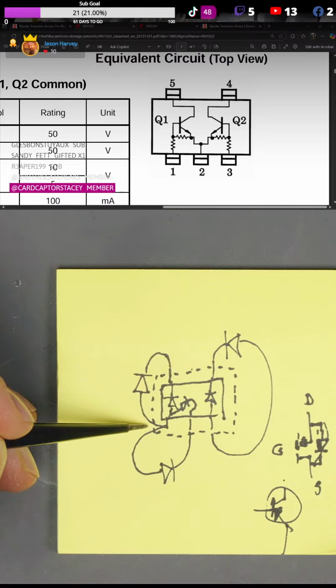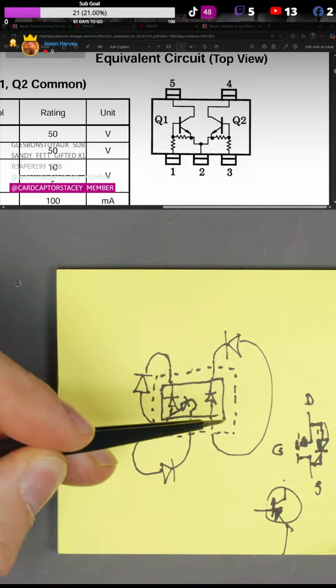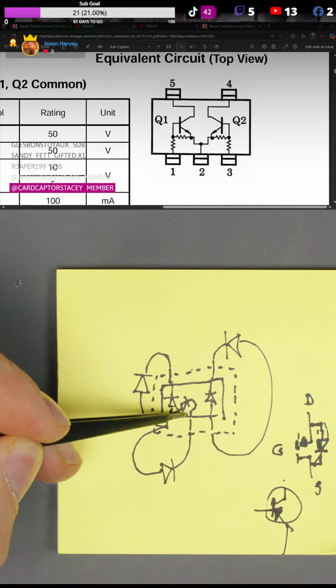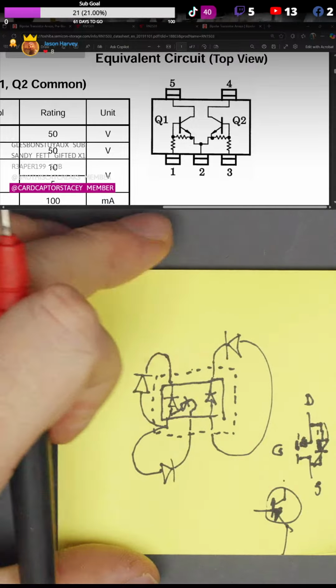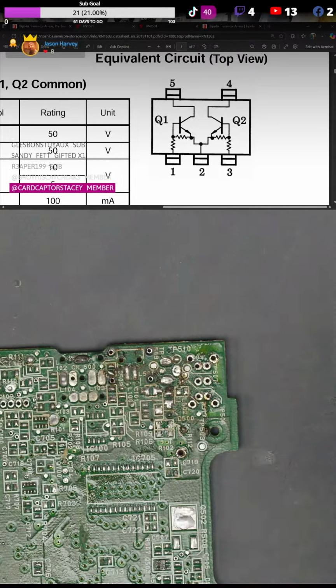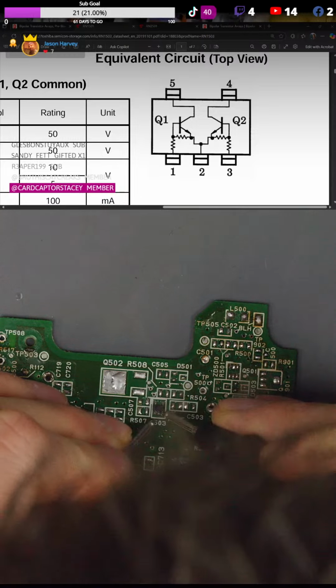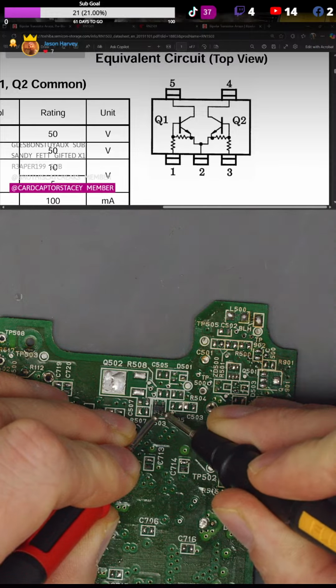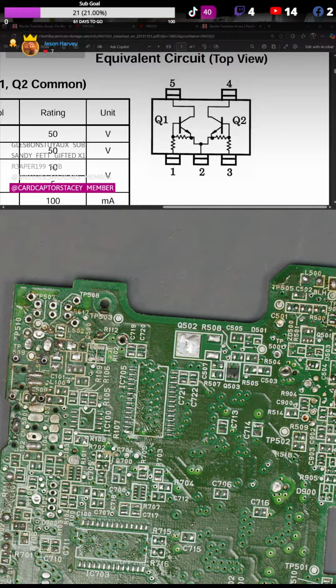We don't have, from pin 1 to 2 would go through here, but then you'd expect pin 3 to 2 to have a diode reading. To be honest, if it's any pre-biased diode in this package, that's what we'd expect. So let me just check to be sure. We don't have a diode reading between the outer 2 pins, so meters are working. No, so there's no connection between there, so I can't imagine it being any of these